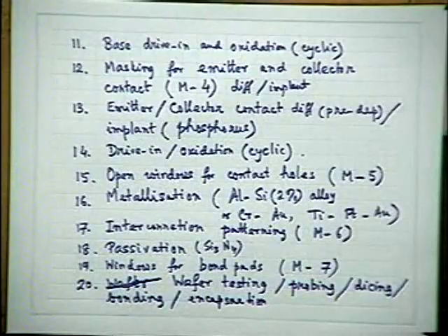After the wafer is fabricated, you have to probe the bond pads using very finely pointed metal probes. Then connect it with instruments called IC testing or device testing facilities. And today everything is digital, all automatic things are available. So you can test the device or the chip, whether it is performing at least at DC level.